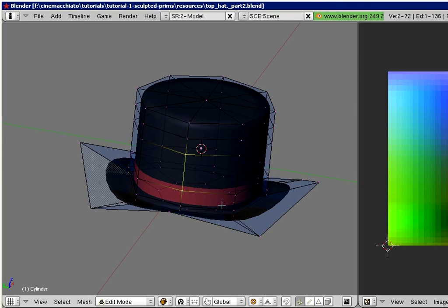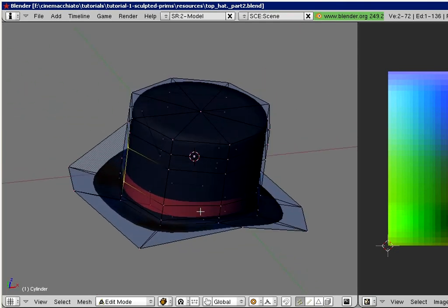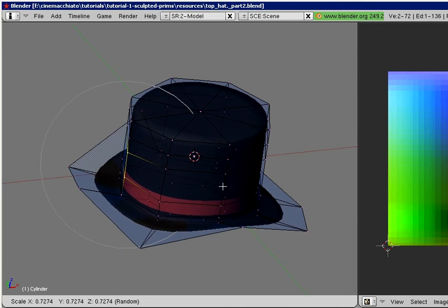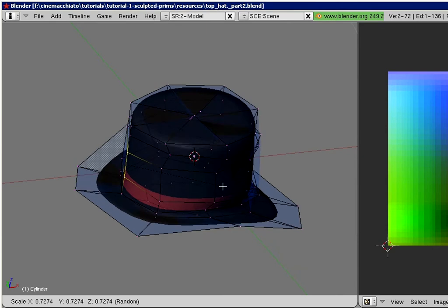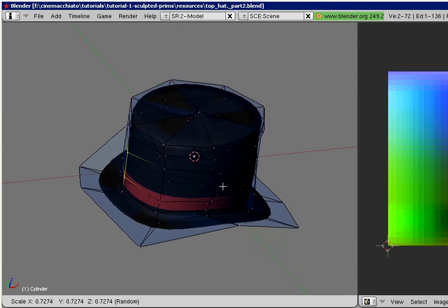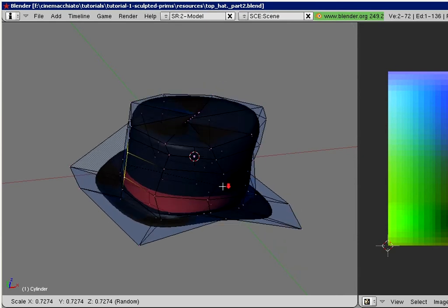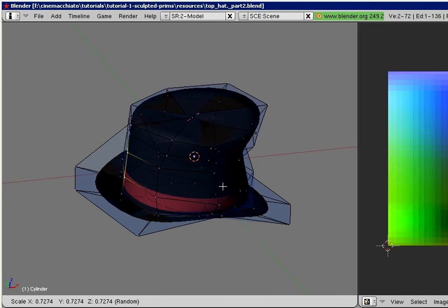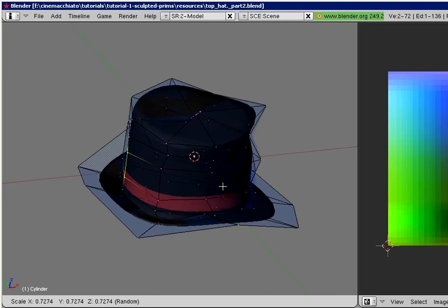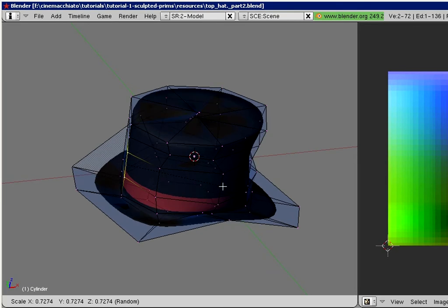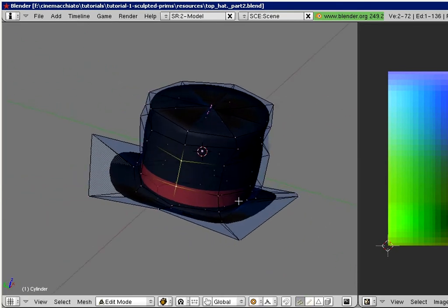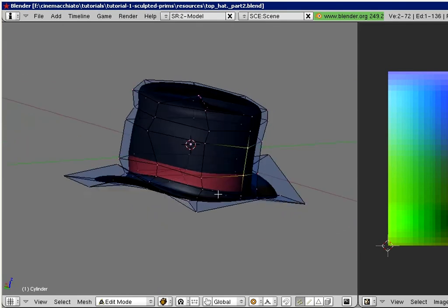Then I scale the column down a tiny bit. At the same time I roll the middle mouse wheel downwards towards me, until the mesh starts to bump up and down randomly. I turn the wheel slowly until I find a pleasing shape. Now I click on the left mouse button, and as a result we eventually get a bumpy top hat.